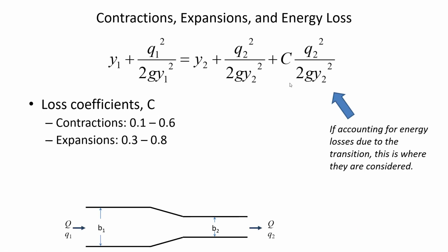So this is something that I gave you a preview on, as one of the homework help type hints. And this loss coefficient allows us to account for turbulence and flow irregularities that occur when a channel gets narrower or wider. And it subtracts out some of the specific energy so that it's no longer available at 2. So that's going to mean that some of the energy that was originally present at location 1 is basically burned in the process of setting up a new channel width.